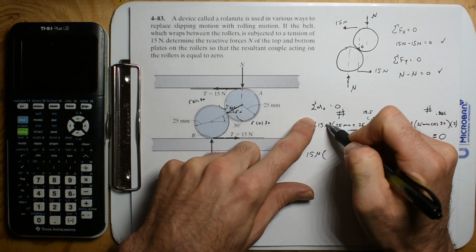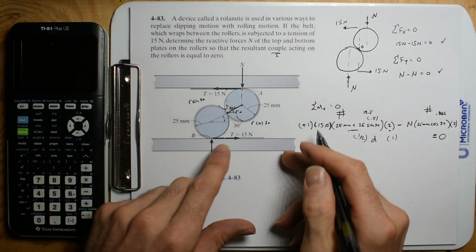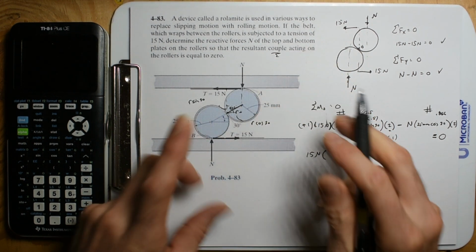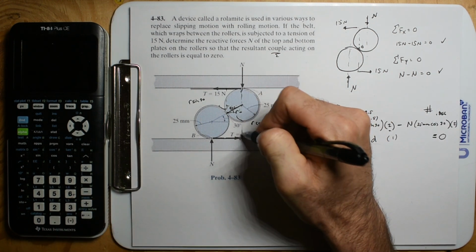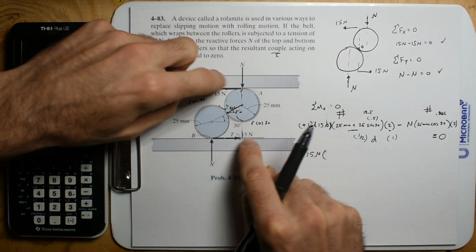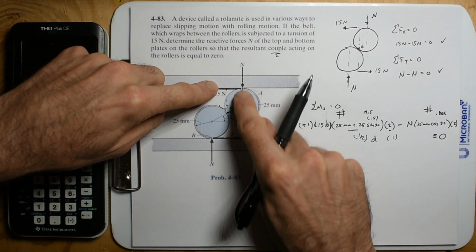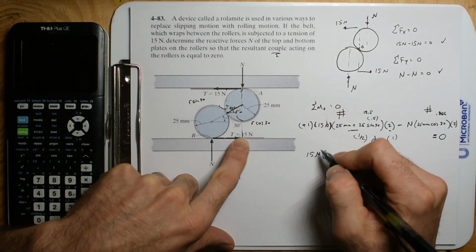So we still take the 15 newtons. That's the definition of a couple, and that's kind of what's going on there. You take the full 15 newtons, and then you take this full distance, but you only do it one time. That's the thing that you can maybe get confused with couples. You identify that these forces are equal, and that's the definition of a couple, where you have two equal forces separated by a distance. So you take one of those forces, 15, and then multiply it by the distance.